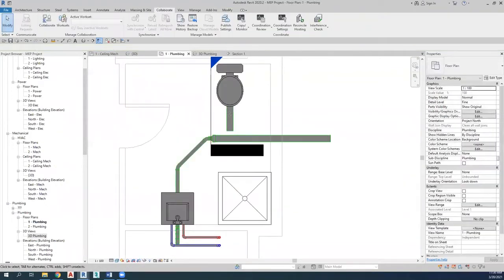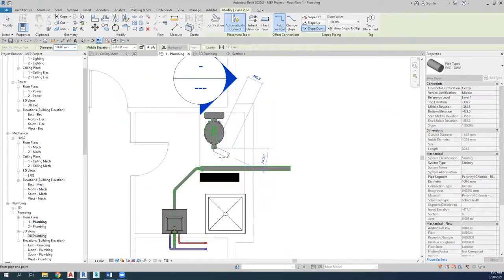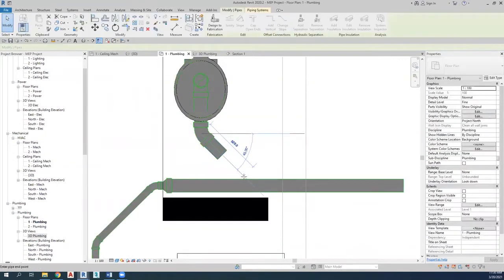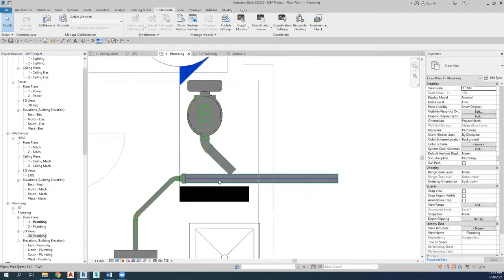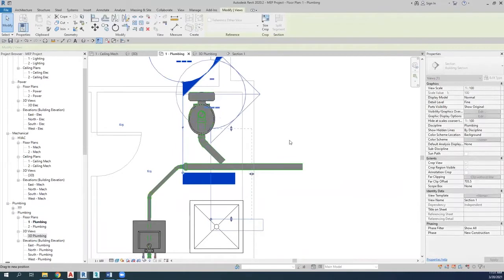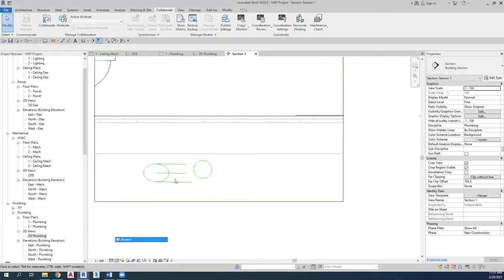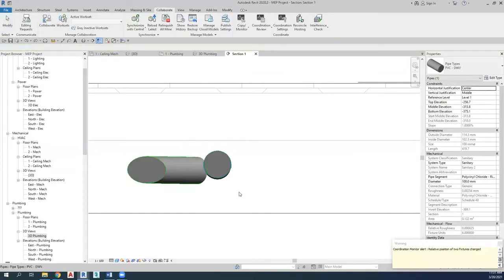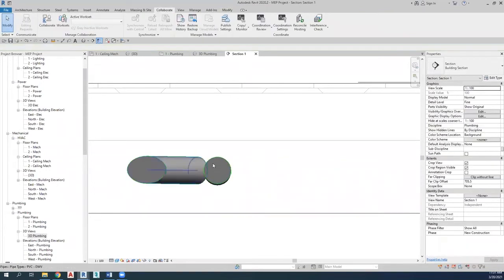we draw the pipe downward, and slope down 1%, in order to attain the resultant pipe. After drawing this pipe, we will make sure, as shown, to draw a 45-degree angle on here, without having to measure each angle individually, seeing as they are implemented. Since both pipes are sloped, it is a bit tricky, but easy, to connect them. So, what we will do is make sure they are visually aligned, and connect them only after that, so that they are well connected, and then we will delete the section and go to 3D, in order to properly observe what we have created.